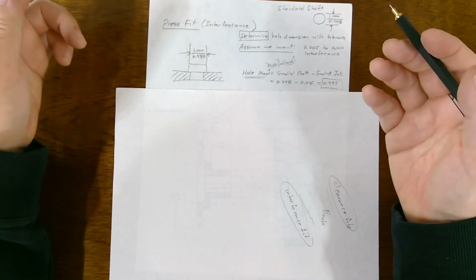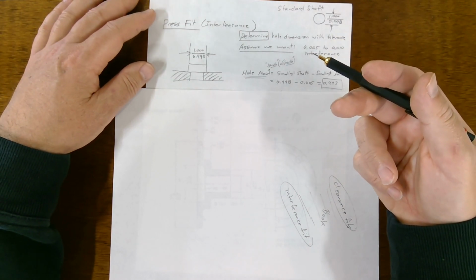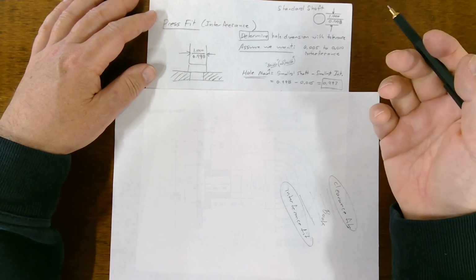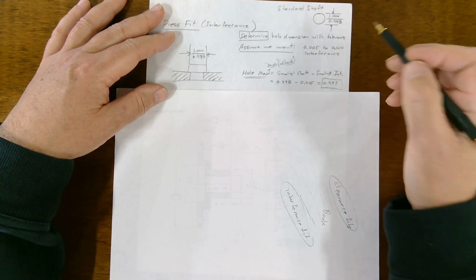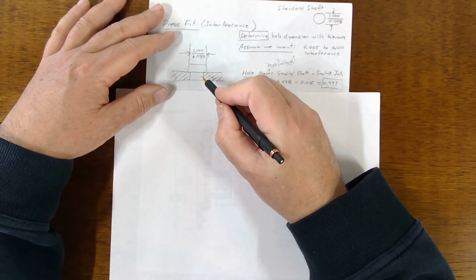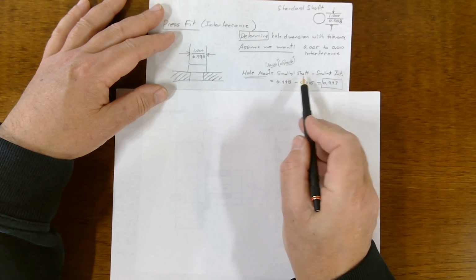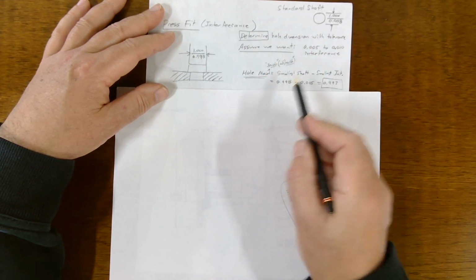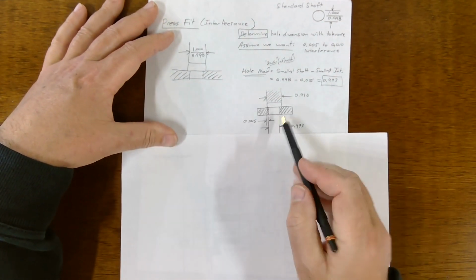Now, it could be lots of factors. It could be material. It could be what the machine or device is being used for, like how much stress is on it. What are the thermal expansion rates? Lots of factors go into determining what this interference is. But let's just say you're given this shaft and you're given this interference. You want to figure out how big to make the hole. So use this formula, right? Hole max is smallest shaft minus smallest interference. Just plug in these numbers and you get the smallest hole. And then that looks like this.